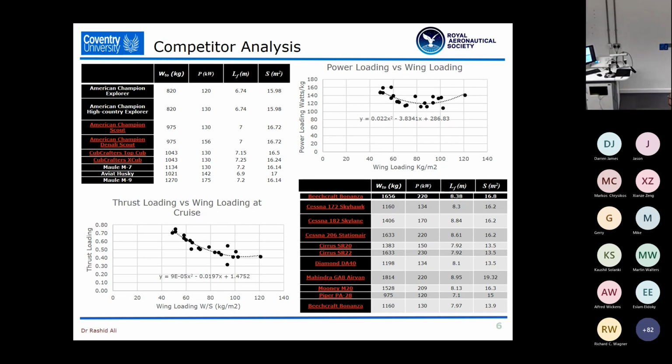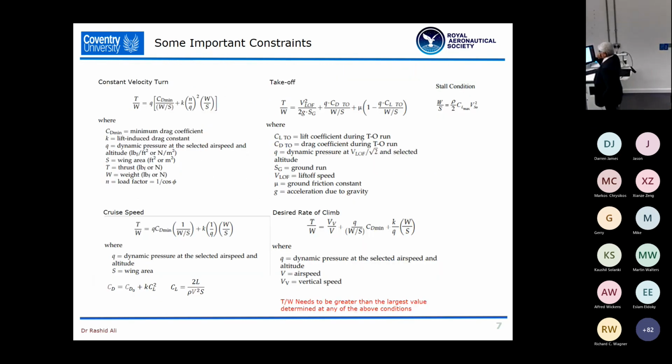So what we're looking at this stage is to have a thrust loading which is going to allow you to overcome the drag and still have enough excess power available to do some performance. So being in the right area to start off with in the design process is the key. Now, analytically, the wing loading and power loading or thrust loading are analytically tractable or definable.